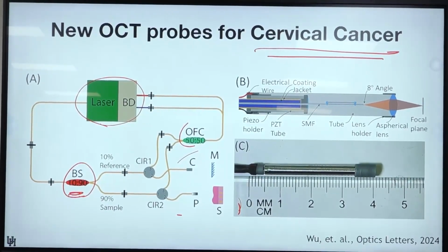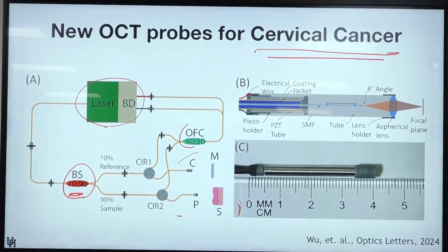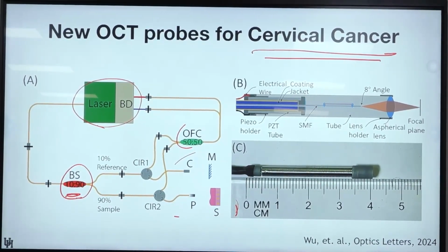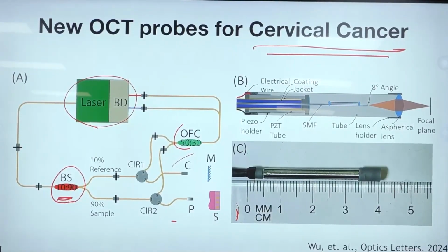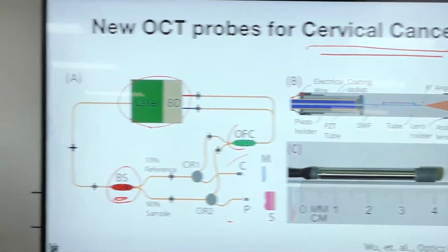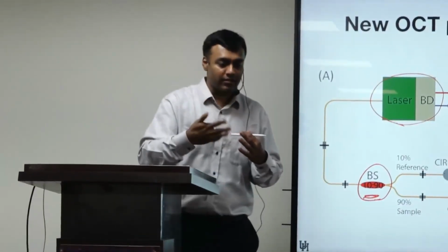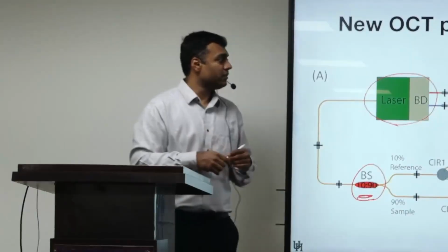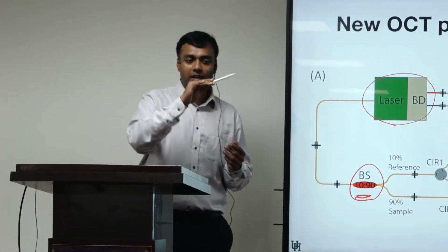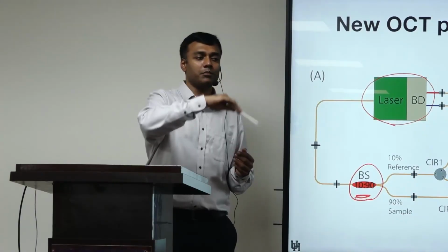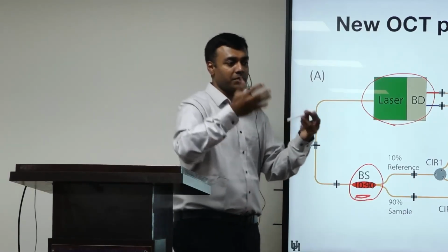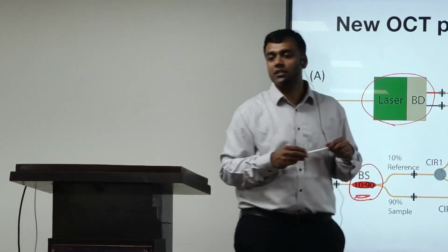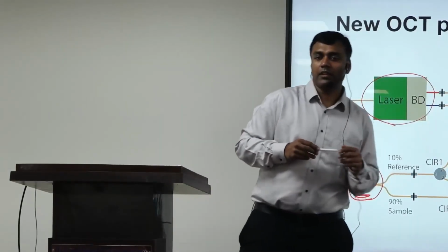How many of you have heard the concept of resonance? Yeah, so some of you. Basically, for many systems, if you apply the correct input at just the right frequency, in this case a voltage, slowly the mechanical amplification builds up. The small deflection keeps increasing and increasing until it reaches a steady state where there is a very high amplification.